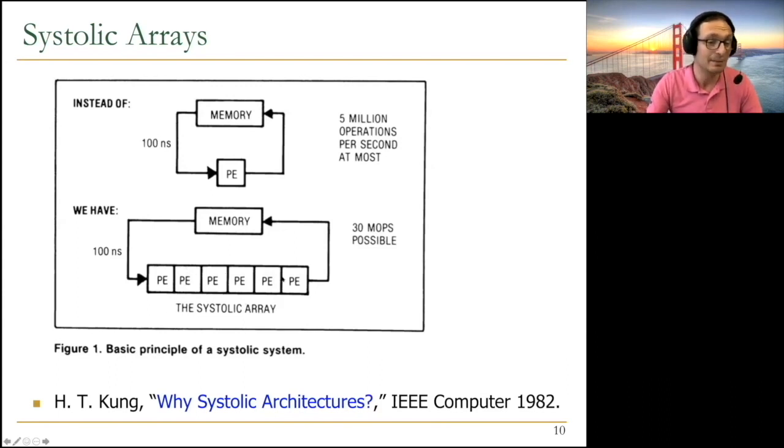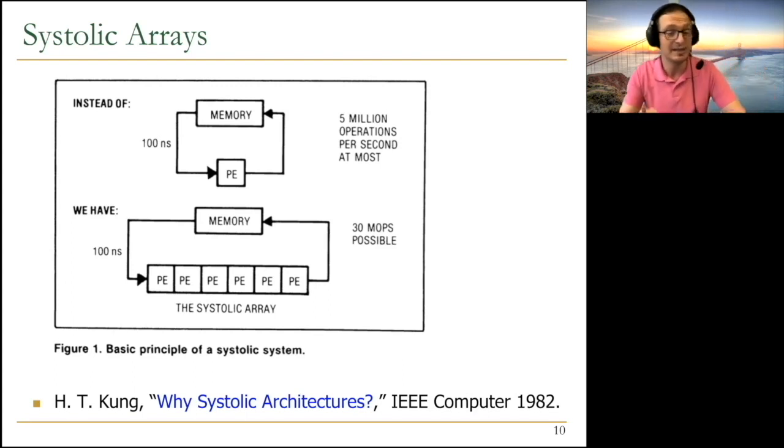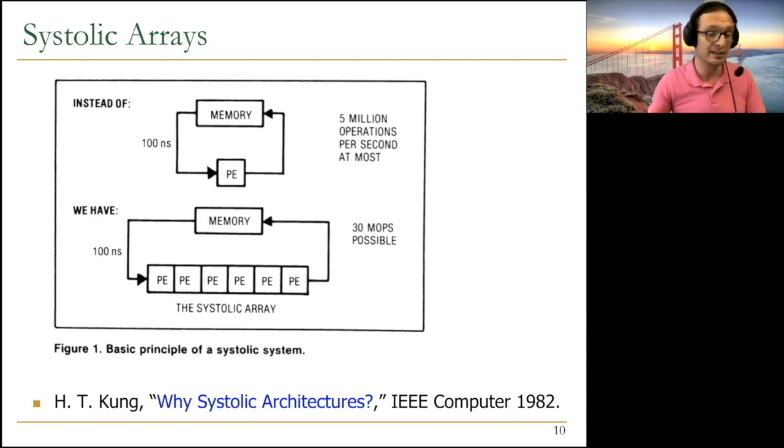And this is one example of a systolic array. You have 6 processing elements. But as we will see, systolic arrays can be 2-dimensional as well, or not so regular as well. They may have different diagonals as well. We will see some examples of this. So linear is, of course, the simplest example, right? And the connections can be multidimensional and not as regular as we see over here. Basically, this processing element may be back connected to this processing element also. We will also see the differences from pipelining soon.